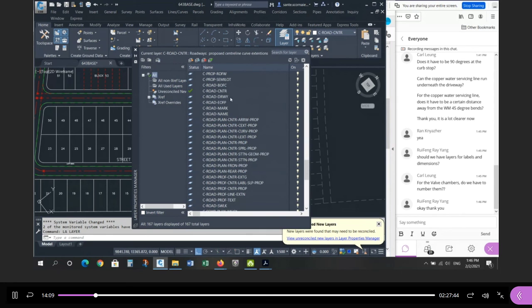If you have a driveway and you're going to label it, copy, paste -text. That's the layer I would put the label on, for the dimension. Edge of pavement: if you need to label the edge of pavement, we go in here, copy, create a new layer, paste -text, and now you've duplicated the layer. One layer for the item, one layer for the text or the dimension for that item. And that's the general idea.